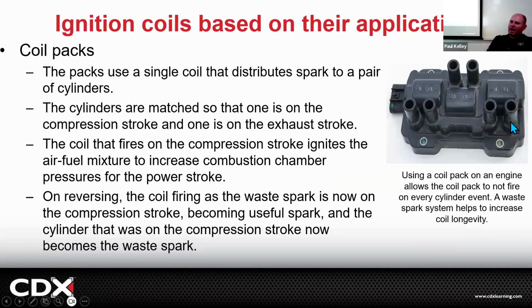Then if we went to the coil pack, this is going to fire for cylinder 6 and 3, this one for 5 and 2, this one for 4 and 1. So this has only really got to fire once per revolution, so 2 times for every 720. But this one also twice and this one also twice. So older Jeeps have those kind of packs, right? Everything used to have packs like this.